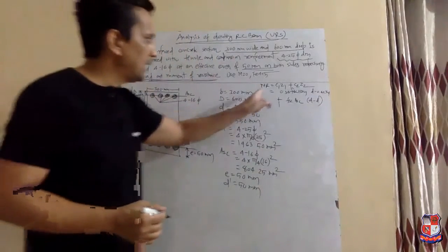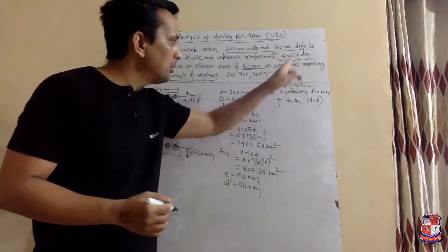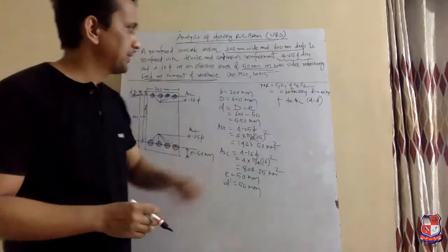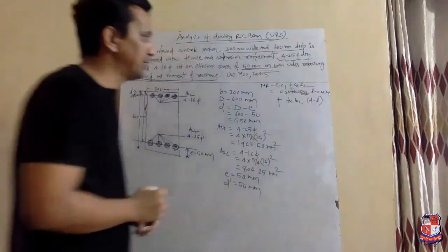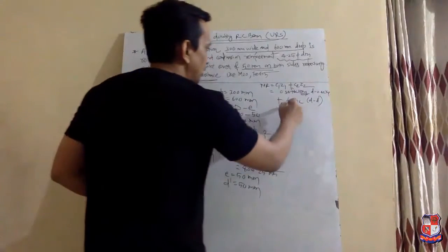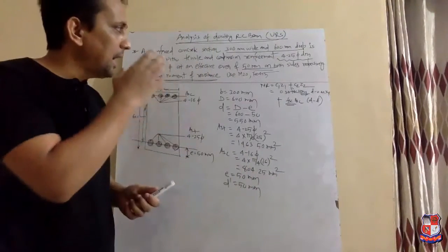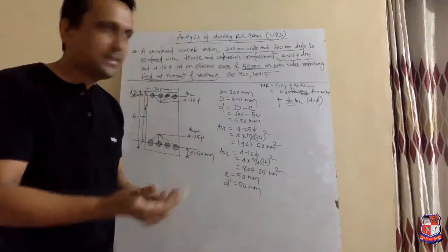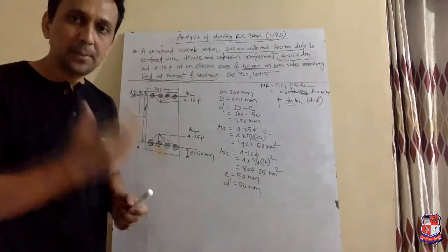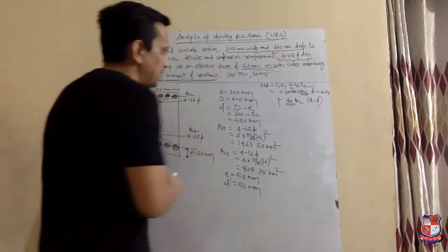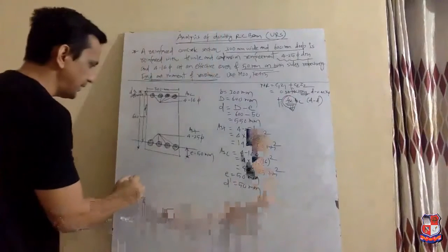It means in this equation, unknown values we need to find first. See, in this equation, the first unknown is xu and the second unknown is fsc. If we find xu and fsc, then we can easily calculate the moment of resistance of the beam. So in this case, first we find the value of fsc.